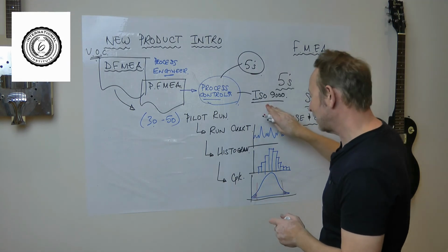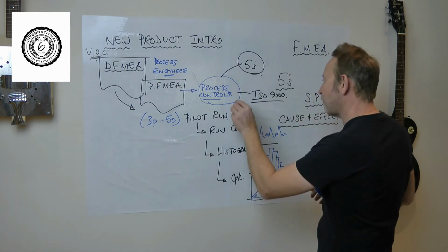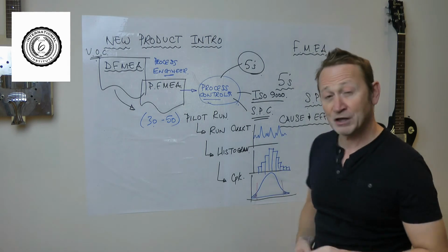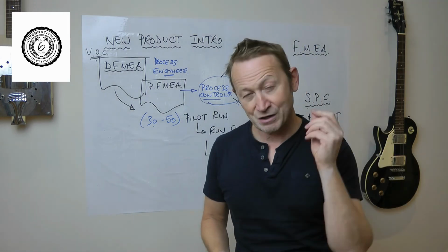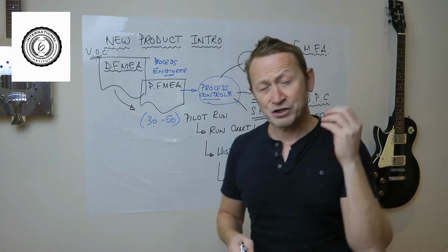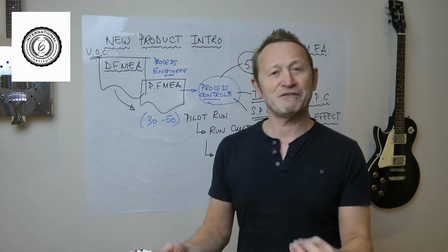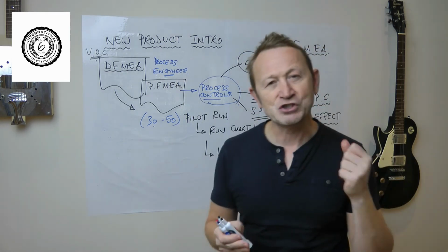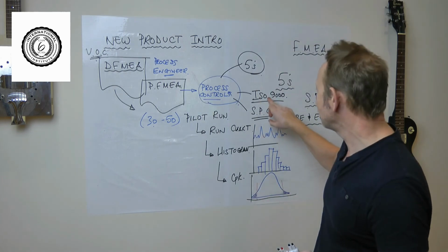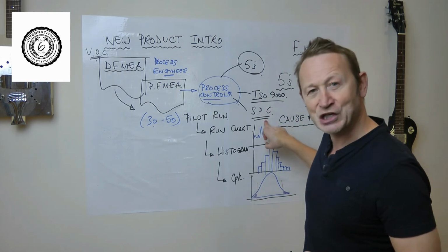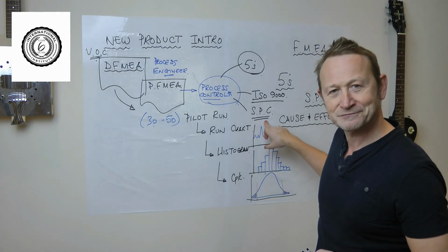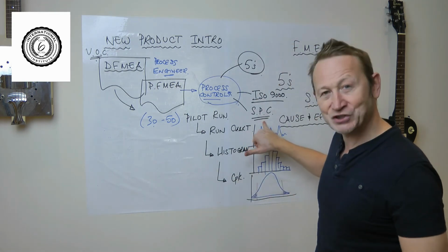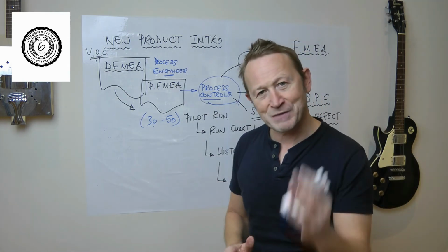Okay, so we're going to visualize the standards. We're going to do regular process audits, and finally I'm also going to use statistical process control, because I can't understand my process properly without SPC. I can't set the process up properly and effectively without SPC. SPC is a fundamental. It is not a nice to have. I know that in ISO 9000 it says use this if applicable. It's always applicable. I don't know why you'd even say that. This is a must-have tool to make the most amount of money.